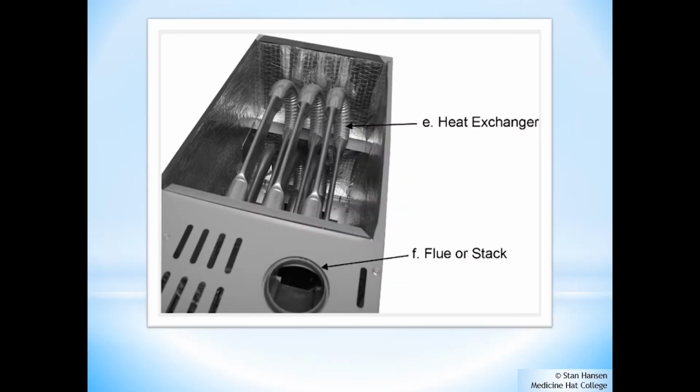When we look at the top view of a furnace, we see two main components. First is a heat exchanger, which is a steel enclosure that separates the combustion system from the circulating air system. So this prevents the combustion gases from being circulated throughout the house. Any hot air from the combustion chamber passes through the heat exchanger and warms up the circulating air. A good heat exchanger will have a large surface area and very conductive material to make for a better heat transfer. We can also see the flue or the stack, which is also called the chimney, and this is how we're going to allow the combustion gases to escape.